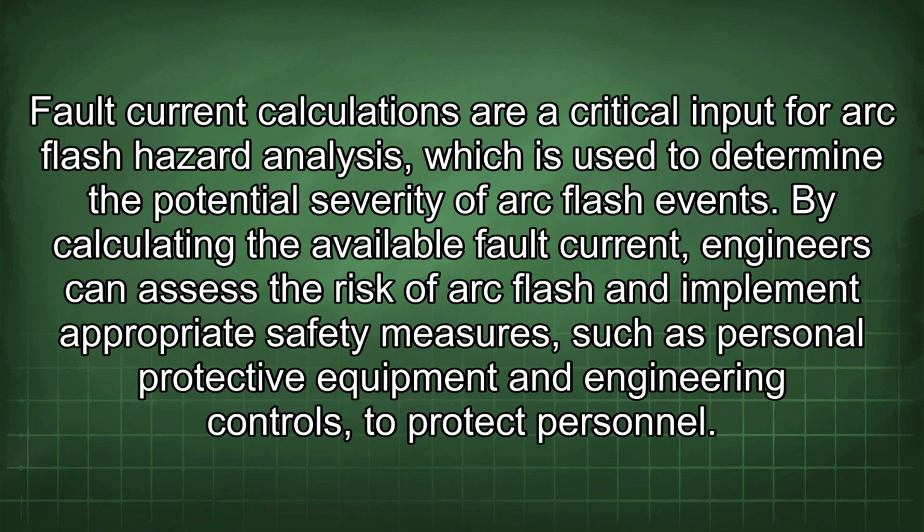Fault current calculations are a critical input for arc flash hazard analysis, which is used to determine the potential severity of arc flash events. By calculating the available fault current, engineers can assess the risk of arc flash and implement appropriate safety measures, such as personal protective equipment and engineering controls to protect personnel.